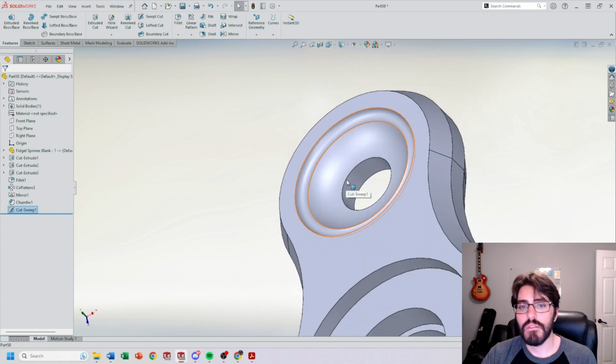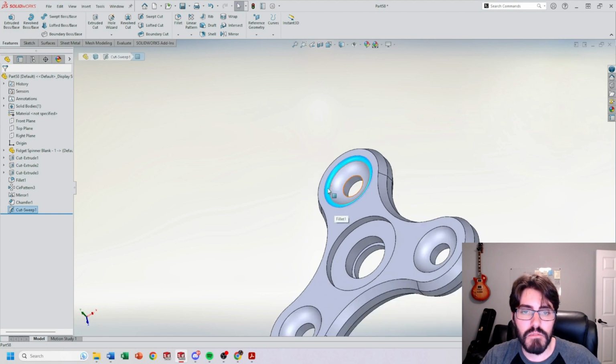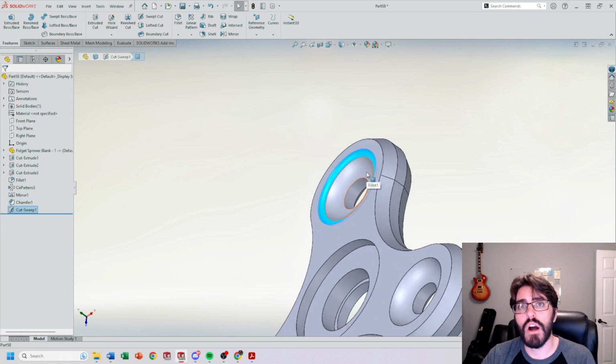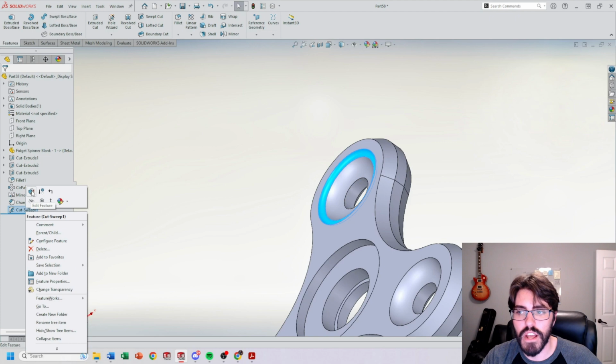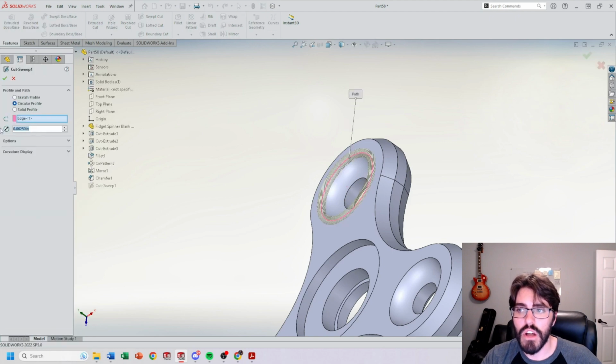This is fine. I have no problem with this. However, I like to have a little bit more control. And if you want, you can pretty much continue on with this video and finish off your fidget spinner by patterning this and then mirroring it once again. However, I want to show you how we can utilize the user-defined profile and maybe control our geometry a little bit better. So again, this is pretty good. You can use this in most instances. Just do that cut sweep like that and then control it. If you wanted to update it, you can right-click and edit the feature, and then you can go ahead and change the values as you need.